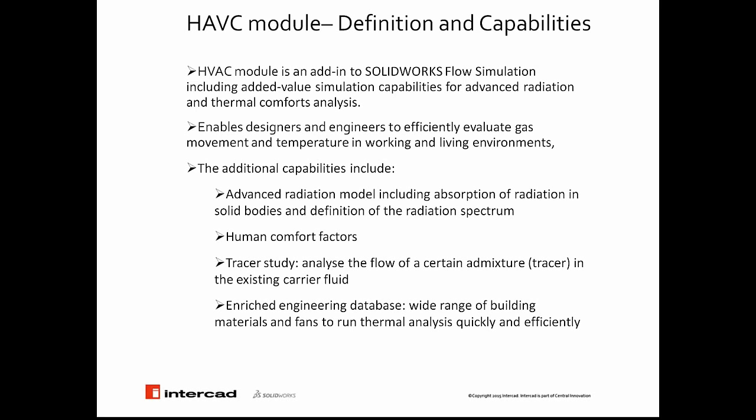To be more specific and categorized, the additional capabilities include an advanced radiation model, including absorption of radiation in solid bodies and definition of radiation spectrum, human comfort factors, and enabling the tracer study, which is an analysis of the flow of a certain admixture or tracer in an existing carrier flow.